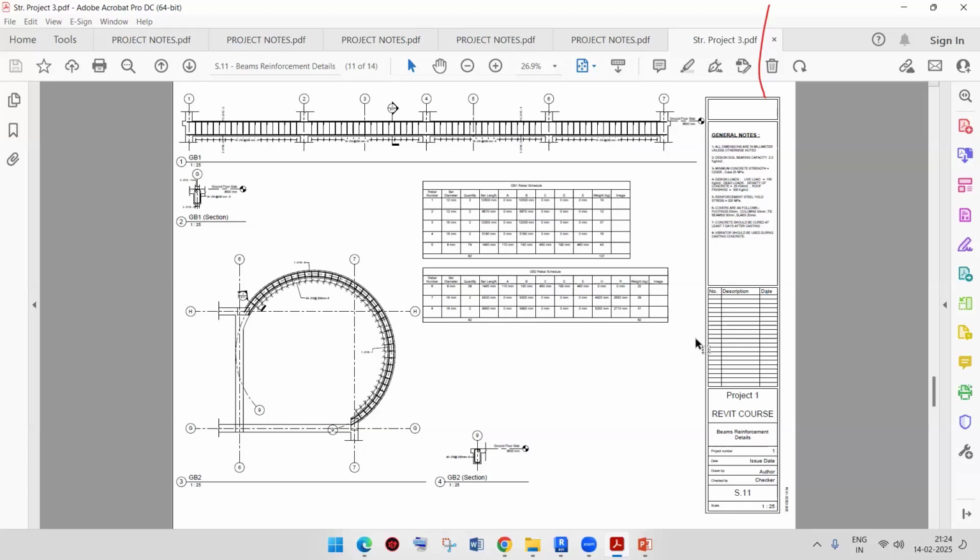then rendering, texturing, walkthrough, and everything. So from the animation, texturing and rendering point of view, I would suggest the best option is any rendering engine solution, either Lumion, Enscape, Twinmotion or V-Ray, but Revit is not best for that. Autodesk Cloud has some rendering engines as well, but it might take more time and a lot of effort. So it's better to use a rendering engine solution. But yes, we can do the modeling in Revit and export that model into Lumion, and that can be helpful to us.